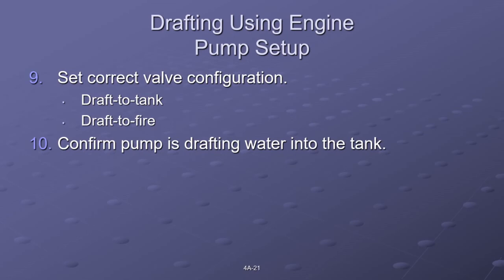Okay, number 9, set correct valve configuration. In the valves piece, we talked about this a little bit, but I'm going to just kind of sidebar here for a second. My methodology for pumping with an engine is a little more simplistic, or maybe not, but the first thing I want to do is figure out what source I'm pumping from. It could be a source outside of the truck, or it could be the tank. Those are my two options, and I open the valves accordingly.